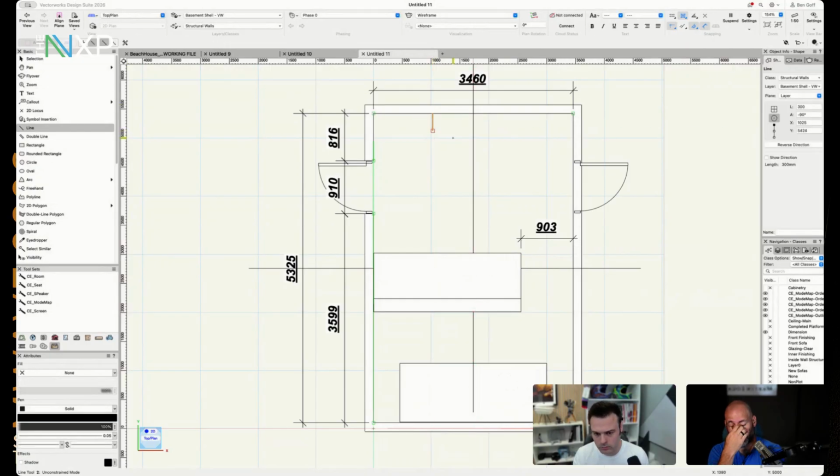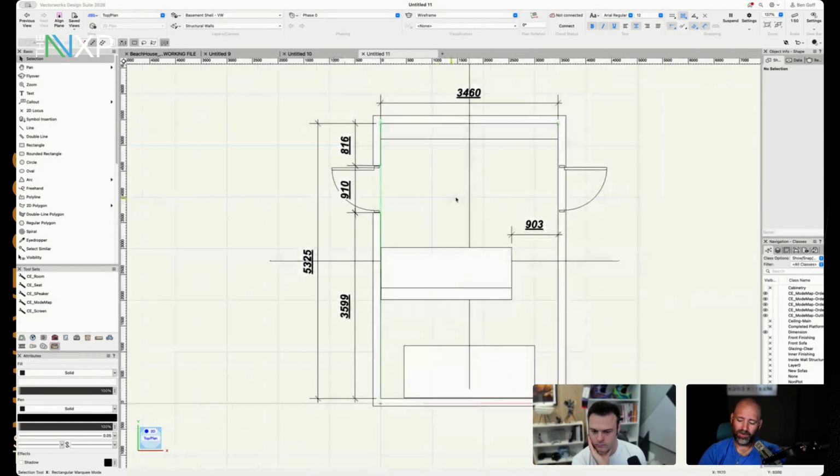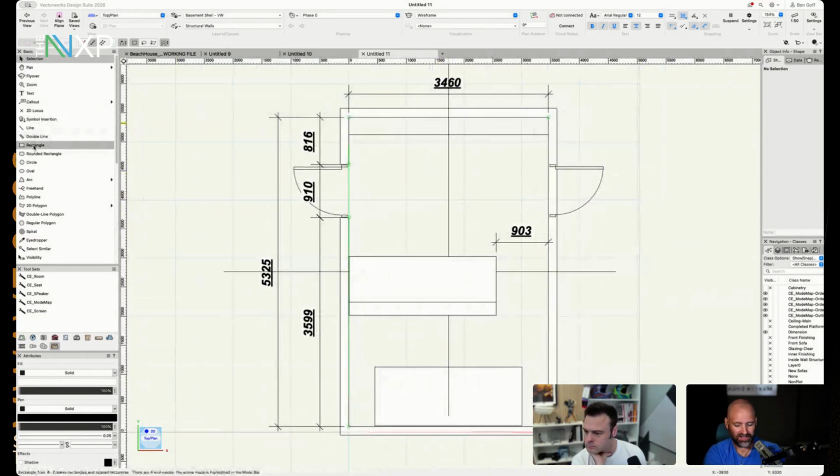And going back real quick while Ben's doing this, putting the screen up, I keep going back to what Thibault said about pressurization. And Ben is absolutely right that we're just defining it. These things are going to move, right? Because when we go in and say, all right, now I know I want this amount of seating, they fit. Now when I say, well, I want some level of isolation and I need to put more mass in the room, and we're talking about resilient clips and double layer OSB and drywall and green glue and all of that. Well, now I'm going to take those walls and I may move them in 3 inches on each side.